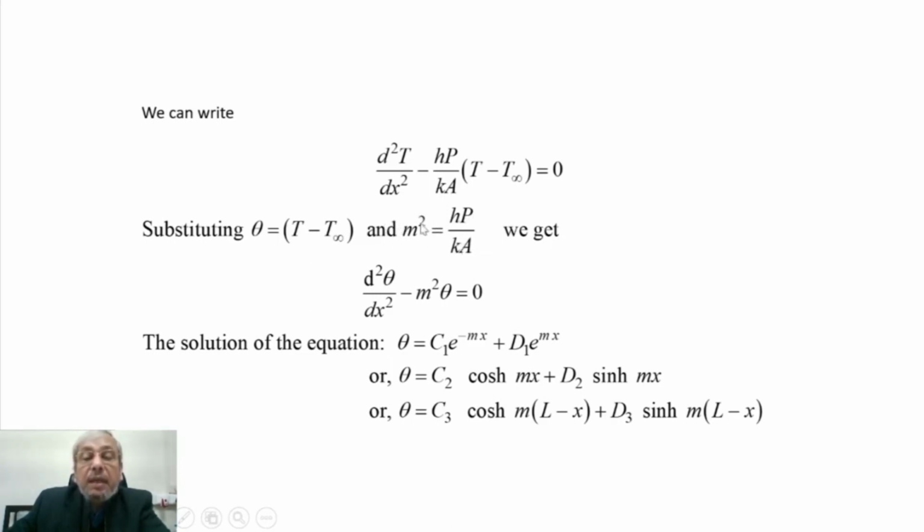m is a parameter which basically comes out of combining these terms, but it has no typical, I would say, physical meaning, but can be interpreted as the ratio of a form of convective resistance and conductive resistance, or conductive resistance and convective resistance, because 1 by h we have to now bring in the denominator, and then readjust the terms in such a way that this heat transfer coefficient by conductivity can be expressed that way.